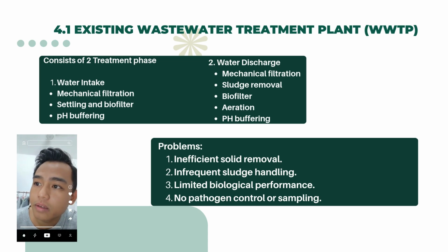For the current design of the treatment, we observe a few problems, one of which is inefficient solid removal. The next one is infrequent sludge handling. Third is limited biological performance. And lastly, there is no pathogen control or sampling.